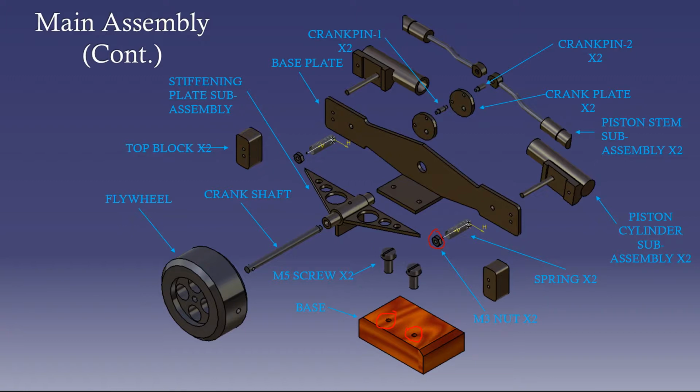Using the CATIA parts catalog, I imported these 2 M3 nuts. However, this time the diameter was defined in this piece right here, the piston stem. Aside from that, everything else was relatively straightforward. Some pieces that gave me some difficulty included the spring, because using GSD, there is no surface for me to constrain or to do an offset or contact constraint with, so I just used a manipulation tool to have it offset when it was sitting on the piston stem pin right here.